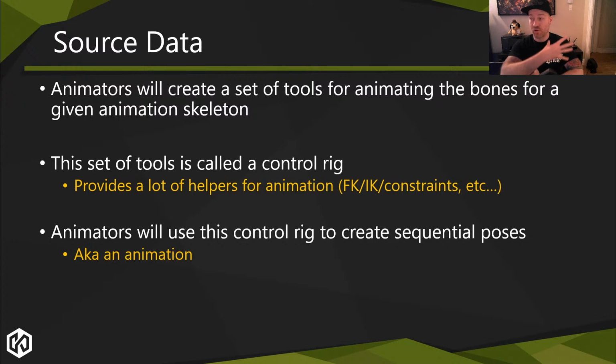So LOD 0 might have a very complex RBF and tons of deformation bones because it's in a cinematic and we zoom super up close and we want to see pistons and stuff move if it's a mechanical thing. But in game, when it's an LOD 1, we don't need any of that stuff. So we would have a different set of deformation bones, and we would have a different setup for deformation bones, which if you're trying to build an anim graph for this is a nightmare, because now you have to say, oh, LOD 1 is this thing, and LOD 0 is this, and LOD 2 is this, and anytime anybody changes a mesh, you have to redo that whole thing. It's a nightmare, and then you have to hope to God that the engine does whatever you have in the DCC, if you even have preview in the DCC, which is a horrific workflow.